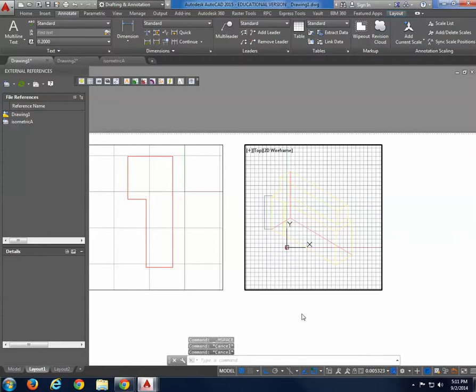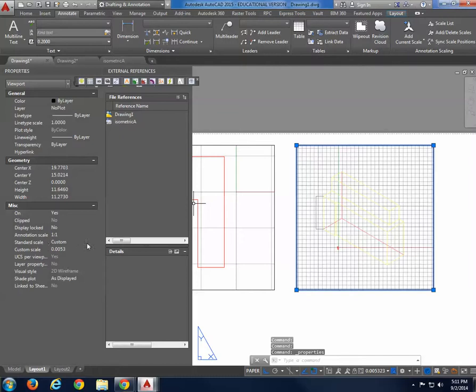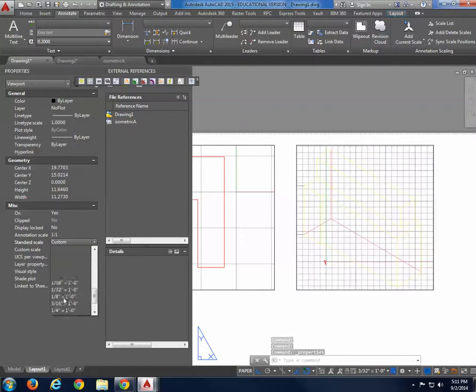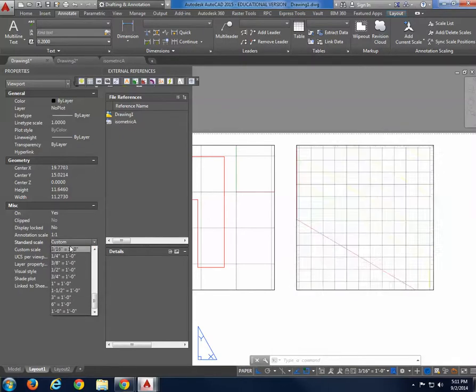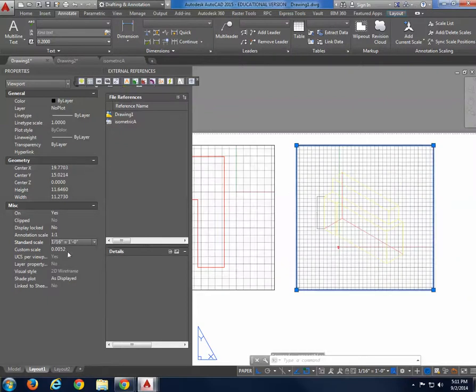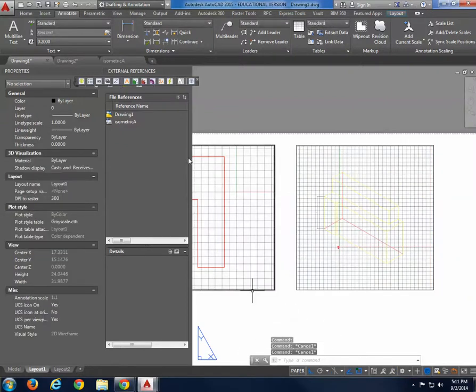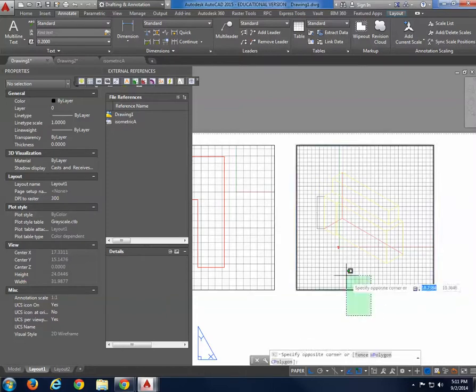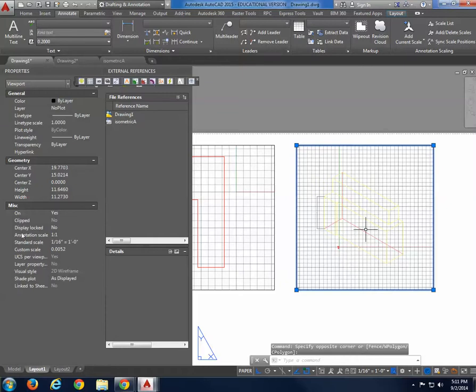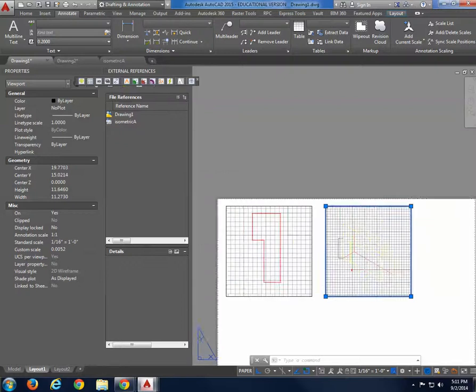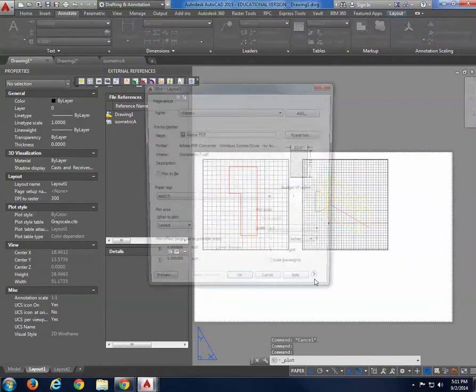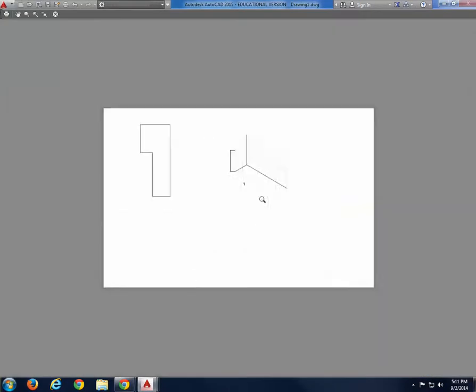the 3D model, no? Remember that the scale is important, so if you press Control 1 on the window, you have the options to see your scales. We want fraction scales, obviously. Control 1 gives you the properties panel, which pretty much tells you everything about everything. So in this case, we need to know things about the window of the viewport. So we select that, and here under miscellaneous, it tells us the scale options, okay? So now I can do Control P, preview, and there it is.